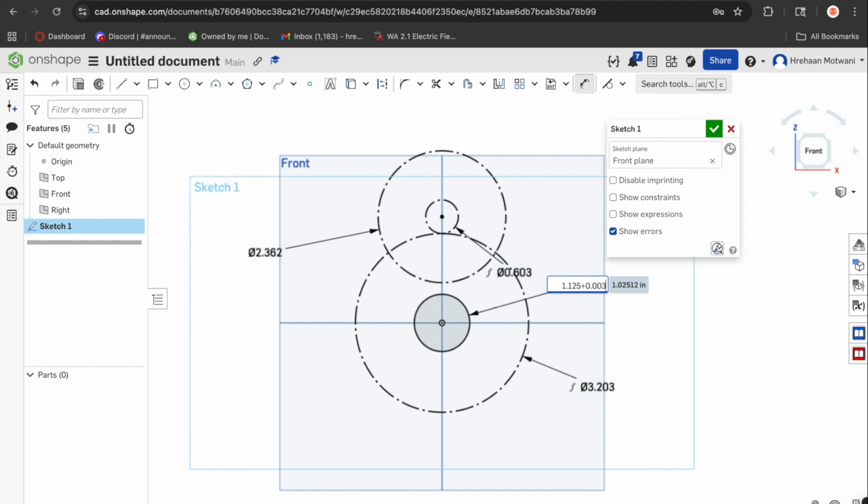So you would add 0.003 of tolerance. For the motor mounting holes, first for the bump in the middle, you would make a hole for that, and the bump is 0.75 inches in diameter, so you would just make this 0.8.